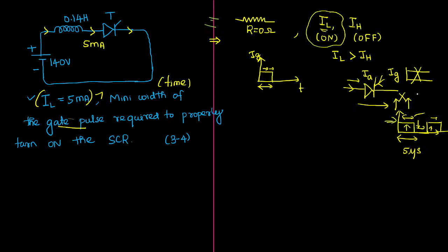Anyway, we need gate current, but we don't need to inject it continuously in order to reduce the effect of temperature losses or to improve the lifetime of the SCR. We have started injecting gate pulses instead of sending continuous current. That's why nowadays you can observe this type of question being repeated in many exams. I'm also observing recently, in many of the exams that I wrote, that these questions are getting repeated. This is the reason; it's a basic application of SCR.